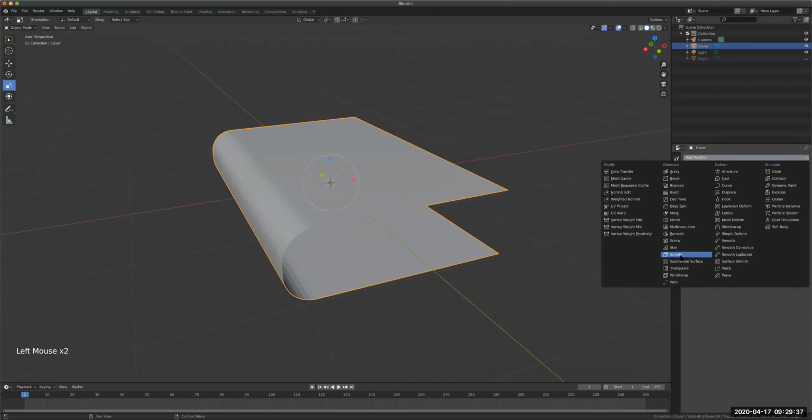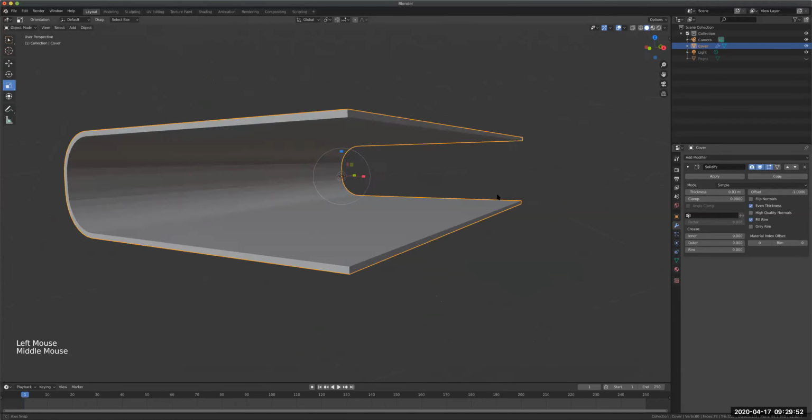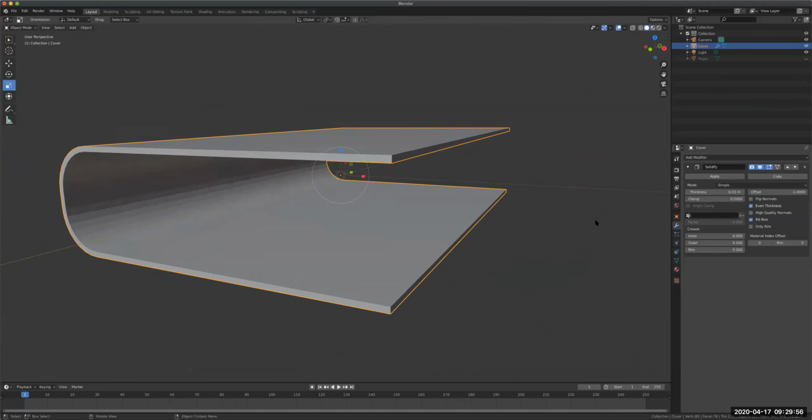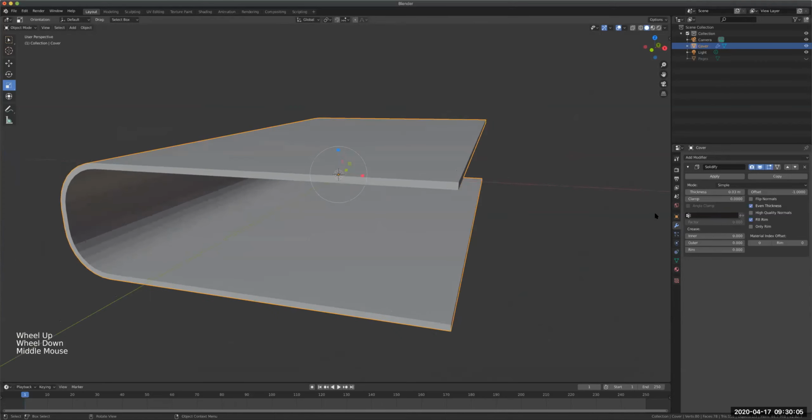There's solidify, a really simple tool to use. All you have to do is mess with the thickness right here. It gives you thickness. Okay, what we want to check also here is even thickness right here. You want to put a check mark on this one, just so that it's equally distributed, right? There might be some organic look to something where you don't click even thickness. It gives you a little bit of imperfection and whatnot, but I don't think you'll notice it. So let's play it on the safe side right here with even thickness.